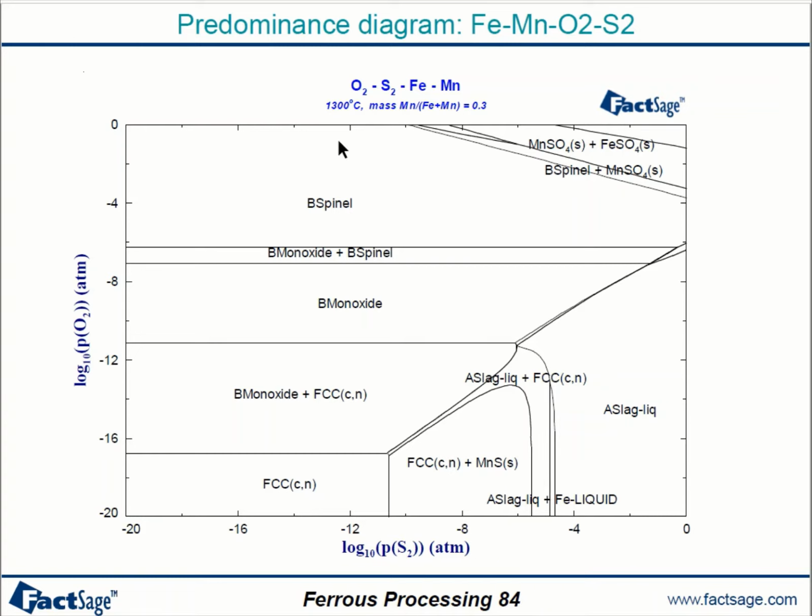So this is kind of the stability diagram or predominance diagram. In the predominance diagram calculation, if you are considering every phase which is forming as a product here is the pure solid or pure liquid phase. When I say pure, this is not the solution phase. When it is stoichiometric phase, it's very easy to do the calculation.